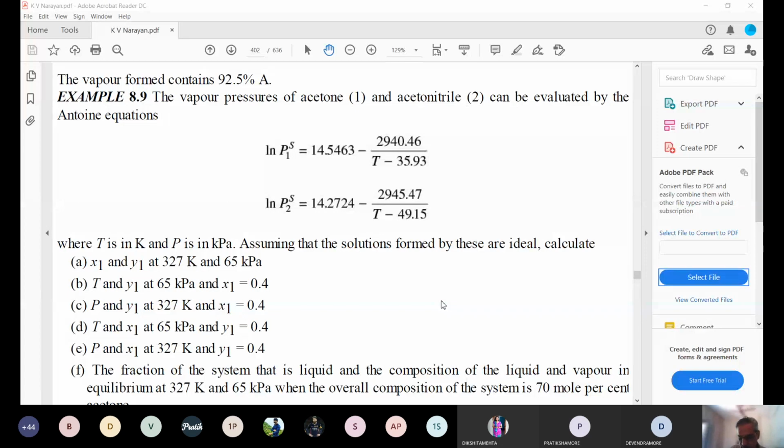And our target is 64.15, that means around 0.5, 0.7, 0.8. So roughly increase the temperature by 0.5. So it's not exact. It's not a linear correlation. Vapor pressure and temperature is not a linear correlation. It is exponential. So we get a rough idea that the change should be less than 2 degrees. You can assume 331 or 330.5, like we assumed. So it's trial and error. It all depends on how good your guess is. That's all.